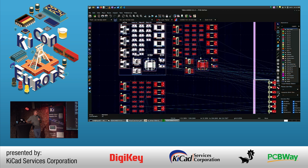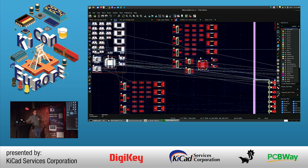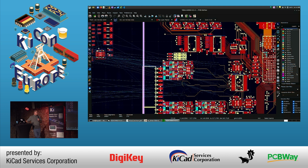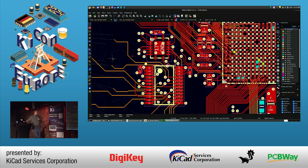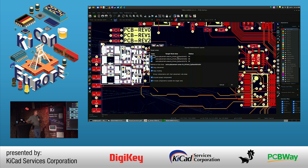There is an option to group the rule area with the components, so that you can move it all together. This greatly simplifies placing things on your PCB. And then in order to duplicate the layout, select the master, the reference, whatever you call it, tools, multichannel, repeat layout. It will automatically detect the rule areas that are compatible with your reference area.